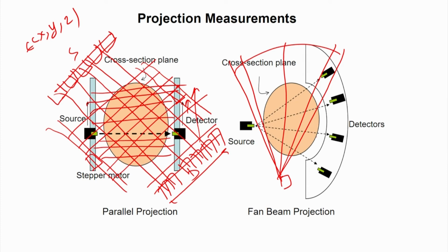The principle being used is I equals I naught e raised to the power minus mu t, or mu l. What you need to do is first scan the empty column, and then scan at the in situ condition to get the volume fraction distribution here.